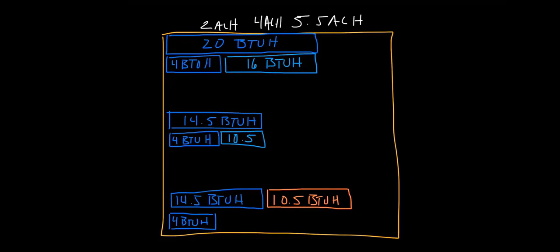The elimination of the parasitic reheat is the single largest reason for hospitals to utilize room recirculating units. In most cases, you can reduce the reheat energy requirements for a building by 60 to 70%. There have also been hospitals that have shown the ability to reduce the reheat cost by as much as 88%. This reduction in energy usage is one of the main reasons for the increased use of chill beams within patient spaces where allowed by ASHRAE Standard 170.